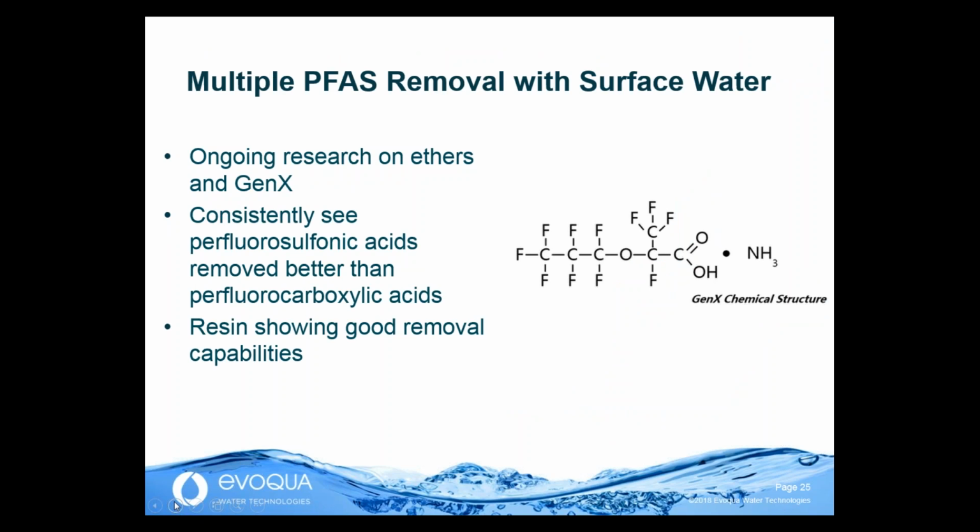Moving on to the next slide. So when I talk about Gen X, I am actually not talking about a generation of people born between 1964 and 1985, or however you define Gen X. Gen X was actually the replacement chemical for some of the PFAS materials that was supposed to be safer. In any case, we have done studies. I'm not at liberty to share those results right now, but what we are seeing is resin is showing good removal capabilities with the Gen X and some of the perfluoro ethers.